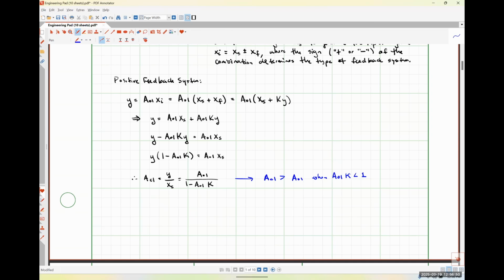So earlier for the open loop systems, we were talking about a linear range of, you know, plus or minus 50 to 100 microvolts. We're talking about potentially nanovolts or less of linear range on a system like this. So for all intents and purposes, we either swing from VCC minus to VCC high or the other way around. There is no linear amplification.